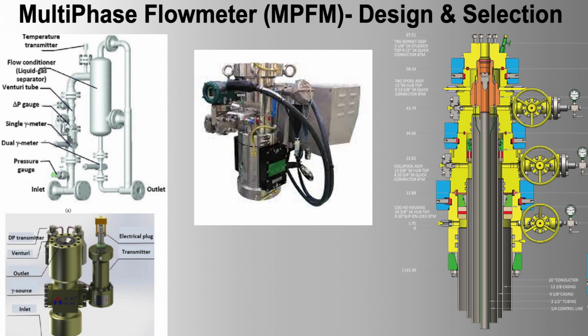5. Enhanced oil recovery, EOR, systems, flow meter type, gamma densitometry-based multiphase flow meter. Material, carbon steel body with protective coatings for specific environments. Installation, positioned for optimal flow measurement with sufficient space for maintenance access. Integration, fully integrated with DCS for automated control and monitoring.